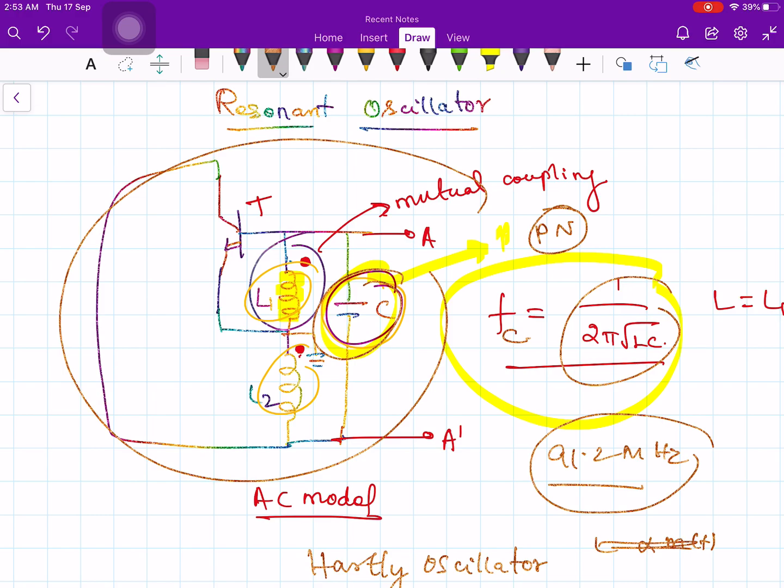The carrier frequency is greatly affected because it again depends on the capacitance C. So even though you don't have frequency stability in the basic oscillator, it is possible to generate a complete system which has other components to give the overall system frequency stability, but that becomes a very complicated system. I will not go into the details of how an FM generator can be made into a stable FM generator, but it can be done, although it becomes very expensive. So these are the pros and cons of the direct and indirect methods.